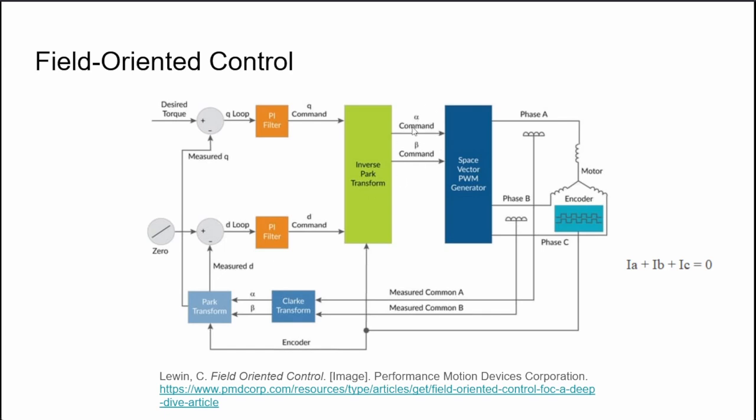And then these rotated commands are sent and they're converted into the 3 power levels to apply to the stators, and the process repeats. Although this whole process requires the use of a microcontroller, microcontrollers are quite cheap these days, and the performance improvement they give makes them highly desirable for the efficiency and smoothness in any situation.